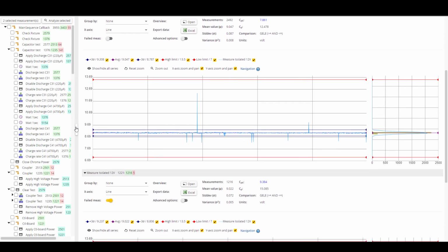And you can immediately see, number one, that the 3 standard deviations dropped significantly. And the CPK value that we calculate is actually the ratio between this range and the range between the test limits. But more importantly, there are several measurements here that are clearly standing out as far away from the average that are not being picked up by the test limits.